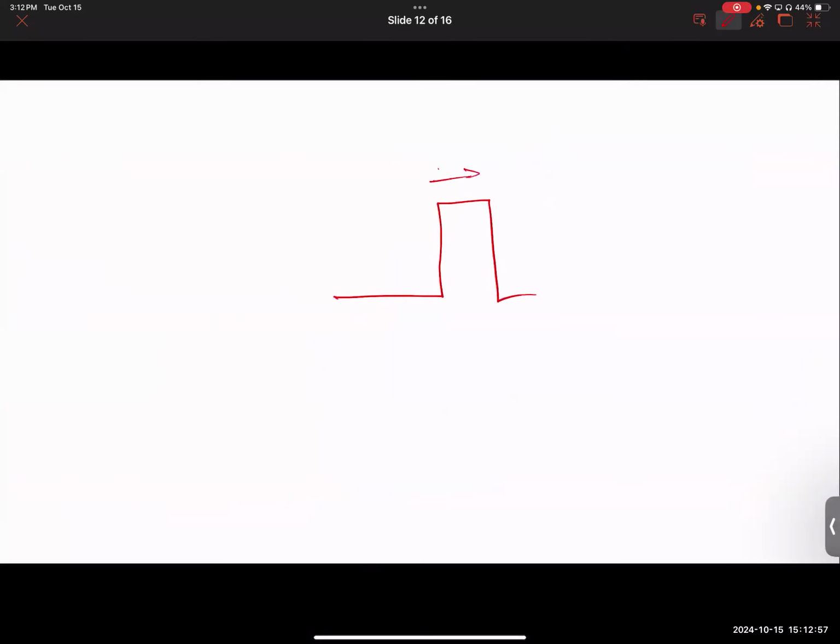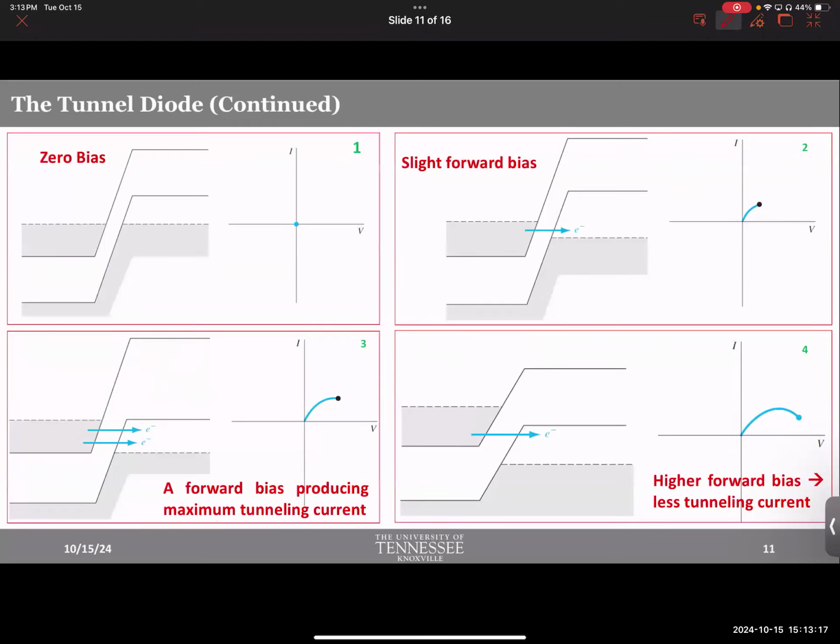So this is the barrier width, say T. The lower the barrier is, the more probable it will be to have tunneling, right? And exponentially more probable, not just a little bit more probable. So if you could reduce the barrier slightly, there will be a huge change in the probability of having tunneling eventually, okay?